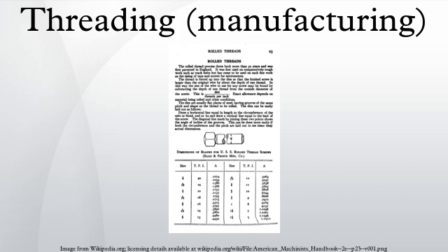Tapered threads can be cut either with a tapered multiple form cutter that completes the thread in one revolution using helical interpolation, or with a straight or tapered cutter whose toolpath is one or more revolutions but cannot use helical interpolation and must use CAD/CAM software to generate a contour-like simulation of helical interpolation.